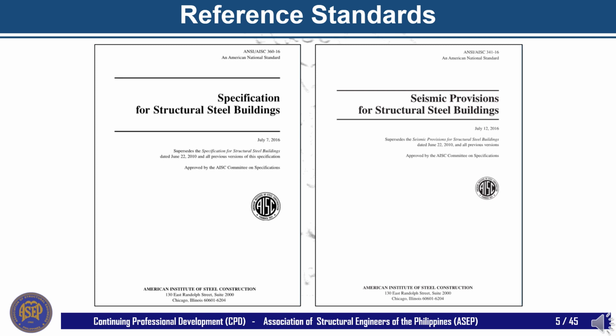The AISC seismic provisions, shown on the right image, was developed to augment the AISC specification, adding provisions deemed necessary for high seismic applications, which require capability to dissipate energy through controlled and inelastic deformations in major seismic events.